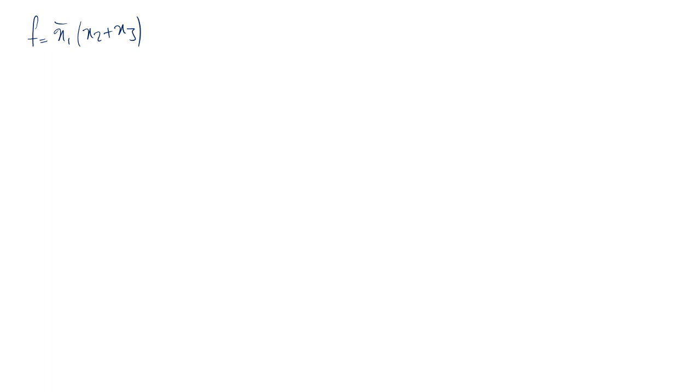Of course, I can say that this is going to be basically an OR gate, and the result is going to be ANDed with x1, well, actually x1 bar. So first I need to invert x1 and then AND that with the OR result of x2 and x3, and it should be done. And I know how to make an AND gate, an OR gate, and an inverter, so I can easily implement this logic.